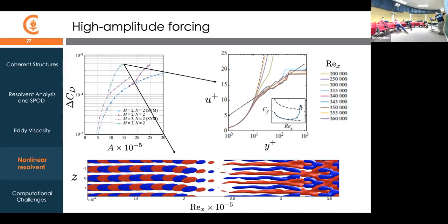And for this very low-dimensional model, where we have just 3 frequencies and 2 spanwise modes in the flow, we're able to not just get these structures, but you can see from the output of the calculation, in terms of the mean zero-frequency velocity field, that as we march downstream in X, starting from this initially laminar case, we get what you might think of as a nascent log region here on the plot.